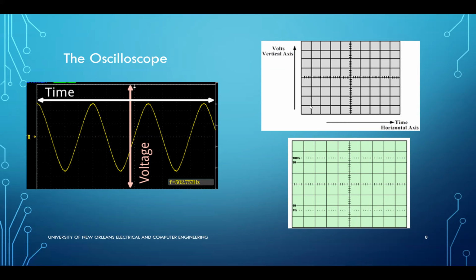In this instance at the bottom here, if I have set up the scope to be 1 volt per division, then the maximum that I'll be able to see will be 1, 2, 3, 4, 5, 6, 7, 8 volts peak to peak. In other words, because each division is set to 1 volt, the maximum that I'll be able to measure on that setup will be 8 volts.